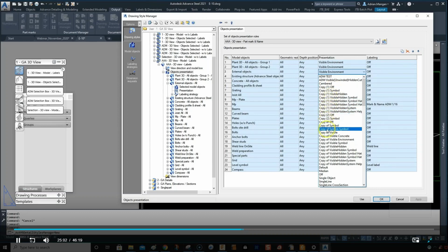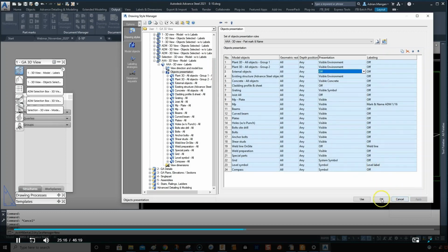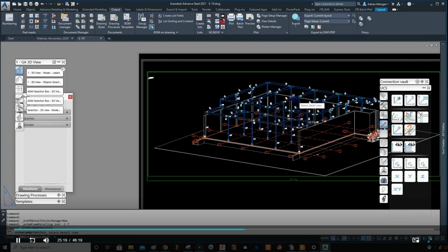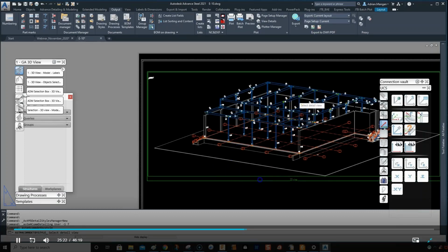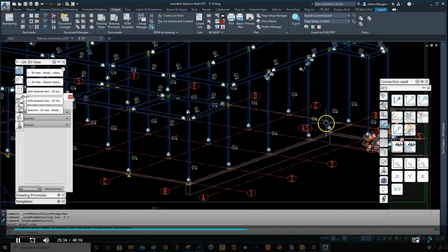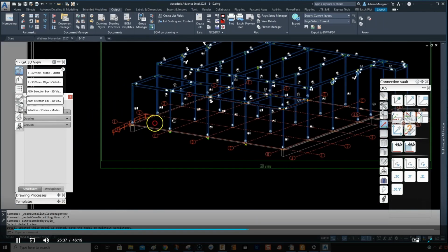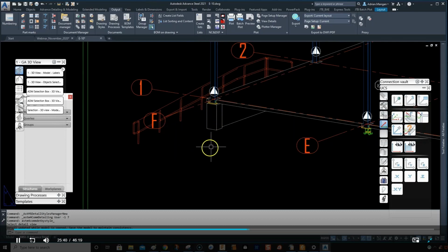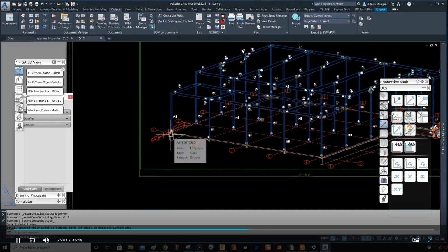As you can see, I did a deep copy once, and this is the mess that I was left with, and I'm in the process of trying to delete all these. So don't do a deep copy at the start, and we want to turn these off. Apply, use, and this should get rid of the concrete on the bottom and the walls on either side. Let's see if it updates. Okay, now we didn't really want to get rid of this over here because it's got rid of the ramp, which I would like to have in there.